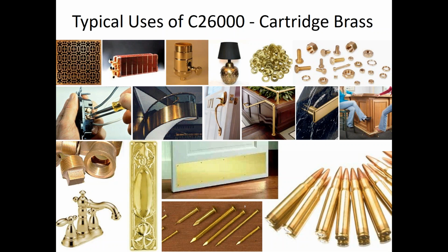But 260 brass is easily manufactured, easily recycled, and at that gauge, conductivity is good, and it makes reasonably good spring components because you got to plug things in and take them out, and plug things in and take them out. And your switches have to operate over multiple years. So 260 was selected. I asked somebody very specifically why they did that. And there you are.